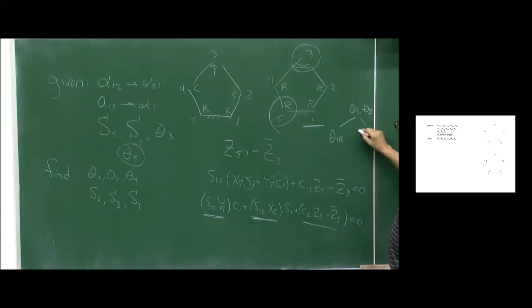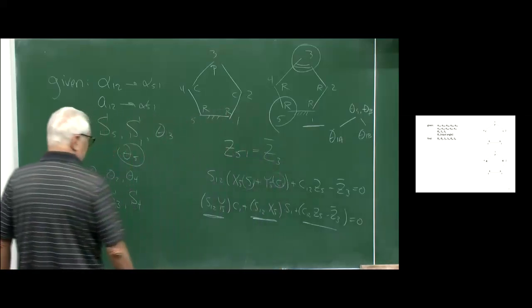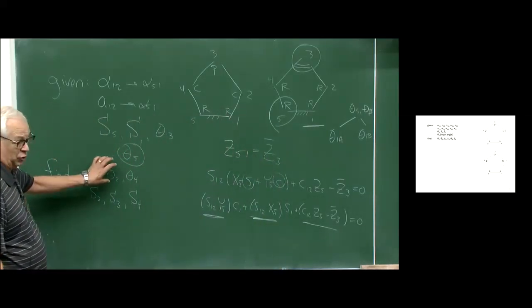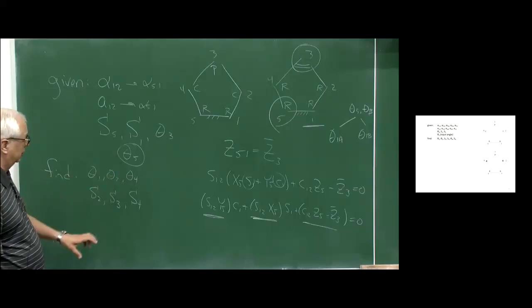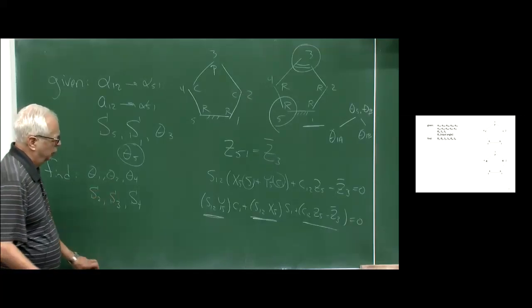And again, I didn't have to solve for theta 1 first, but that's the one that I picked. So boy, based on what we did in chapter 6, it's almost trivial. So a lot of times what we'll say is in these group 1 spatial mechanisms, the problem decouples. You're able to get the joint angles based on what we did in chapter 6, and then we come in and go for those. All right, so next we need to get the corresponding values of theta 2 and 4.